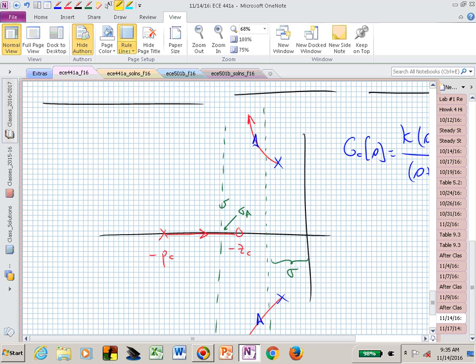Is that the question? So now you're decreasing your settling time. Those curves or those poles will come over, but you'll have to now play with your asymptote formula to determine how do I pick my controller pole and my controller zero to make that asymptote centroid locate it where I want it to be located to achieve my settling time specification.